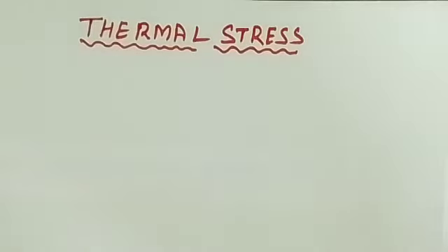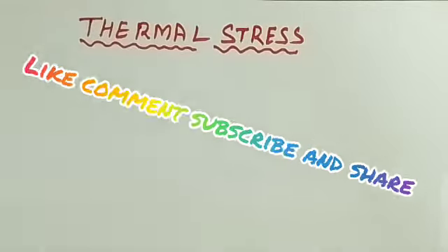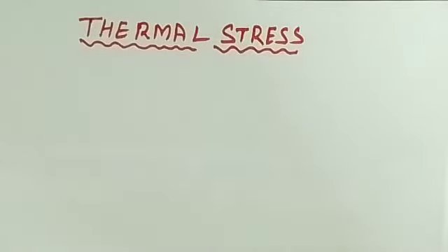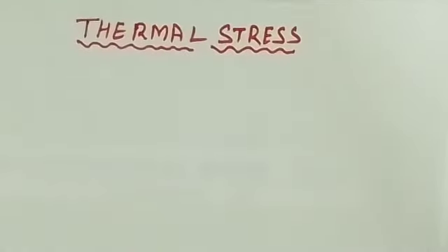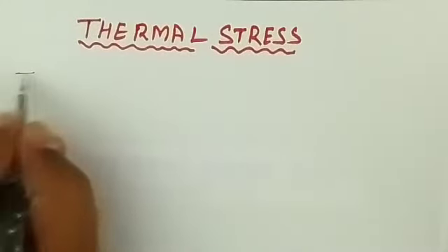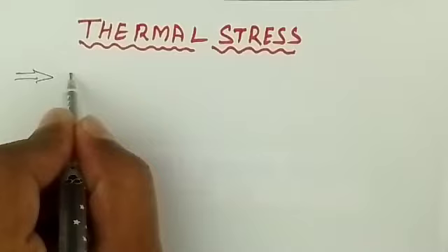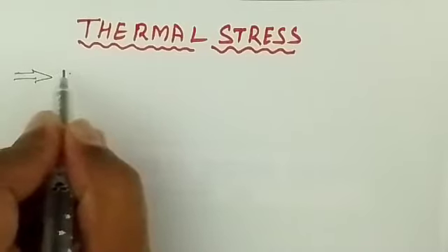In this video, we are going to discuss thermal stresses. So, what are thermal stresses? They are stresses which are induced because of temperature changes. When you have a bar and this bar is subjected to a temperature rise, deformation will take place, which means stresses will be induced, and we call those stresses thermal stresses. So, first of all, what is thermal stress? It is the stress induced in a body due to the change in temperature.